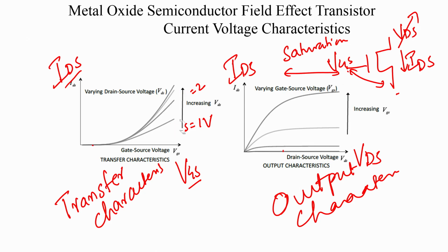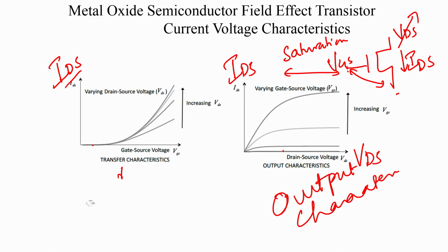Now, what do the transfer characteristics tell you? They tell you that till a certain point there is no increase in current. So, we could define a threshold voltage somewhere. If you take a very low VDS, much smaller than any VGS that you are applying, then the characteristics is almost linear, like a straight line. If you project the straight line all the way back, you would intercept the x axis at the point of Vt, that will be the threshold voltage.